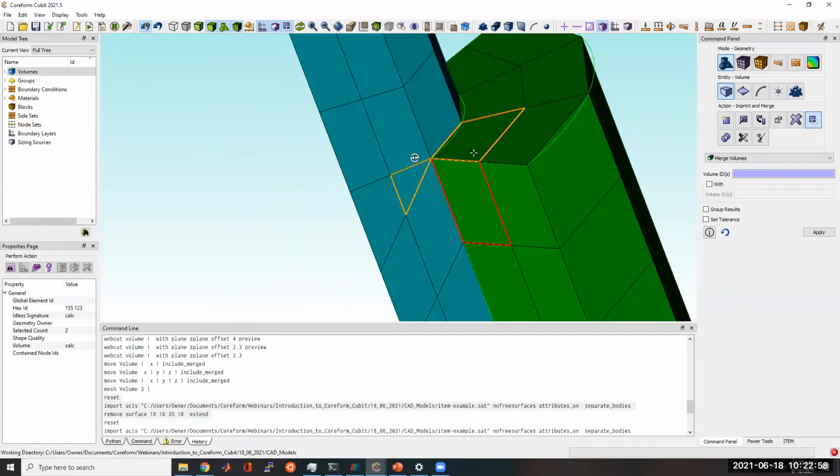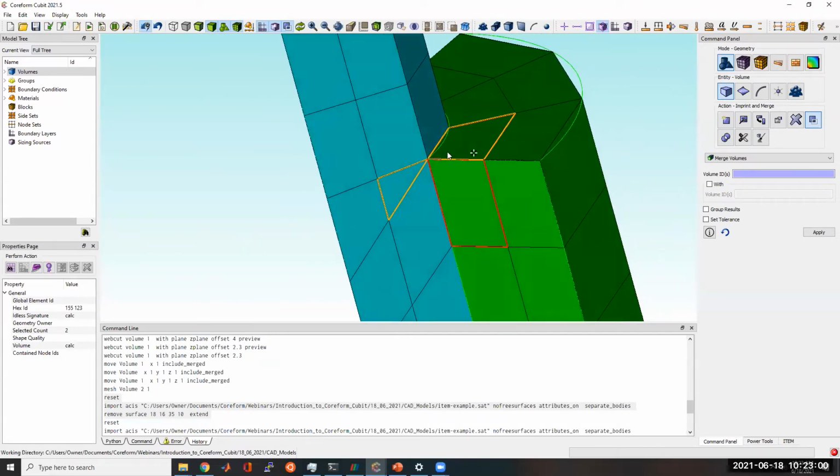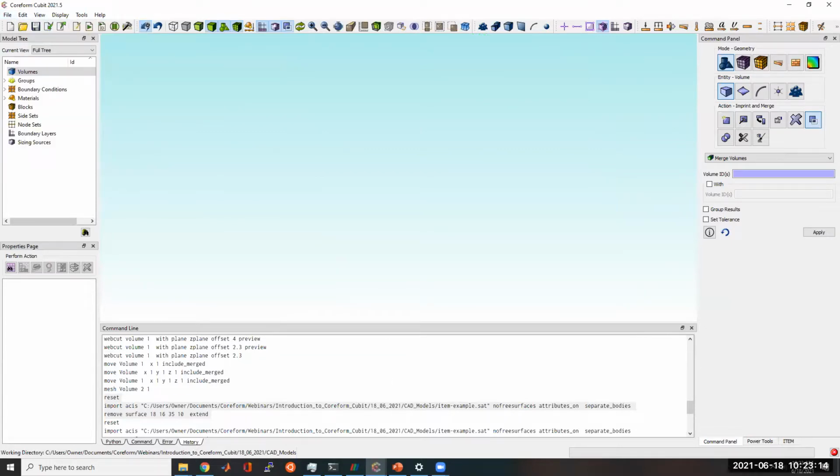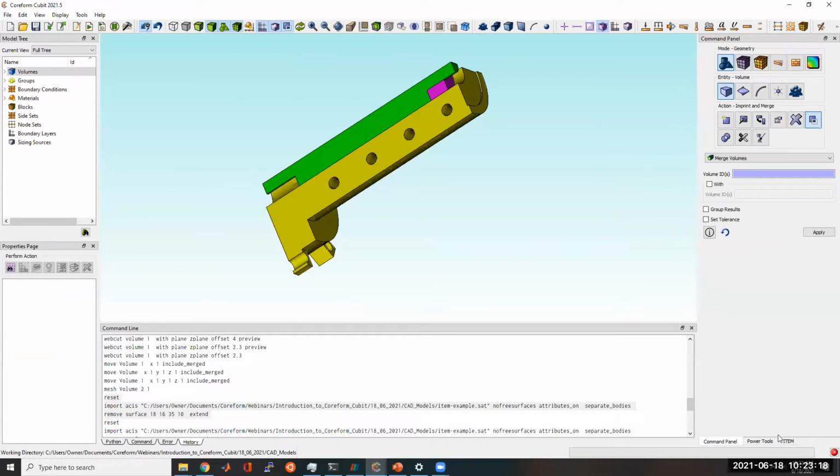So that's one issue with overlaps. They cause bad meshes, but also they're maybe not physical. If you've got maybe steel for one volume and then air for the other, you've got an overlap of materials. So to show how we can detect that automatically, I'm going to just open up my journal file again and play to recover where I had been.